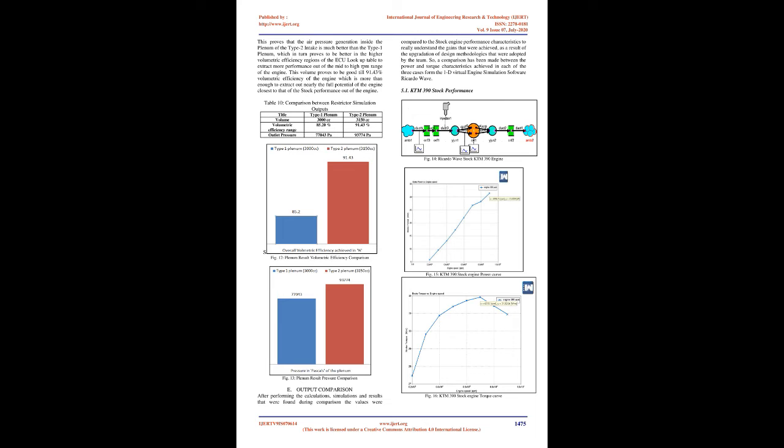So, it is proven that for the flow requirement in the manifold the diameter of the stock throttle body proves to be quite big, which is good for larger volume of air causing lesser choking, but on the other hand it reduces the saturation requirement which the restrictor requires to keep it on par with the stock performance. Hence, the Type 2 throttle body, being of approximately correct diameter, not only delivers the required flow velocity but also is large enough for air volume requirement. To not choke the flow this way, the throttle body in Type 2 is a better choice out of the two.